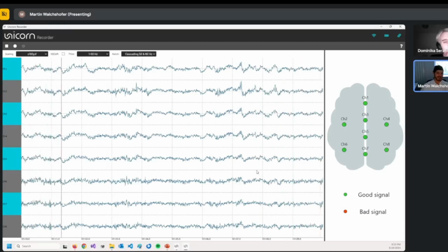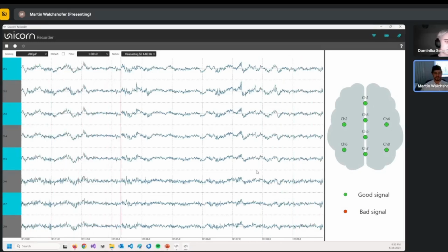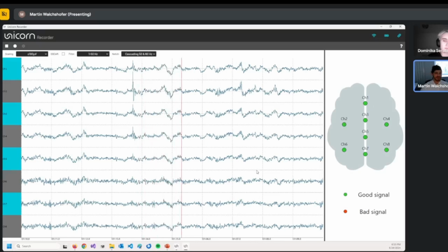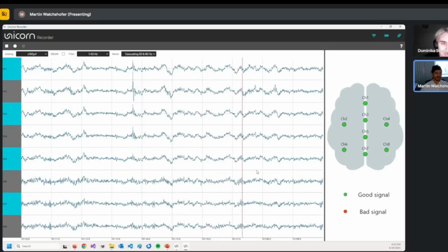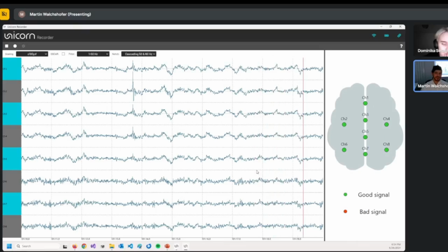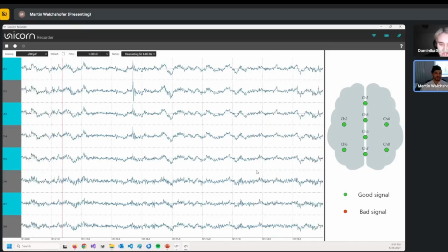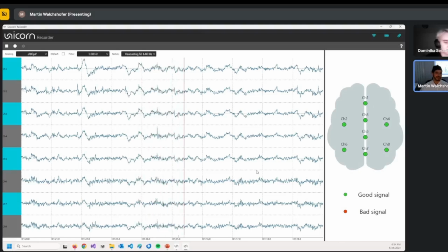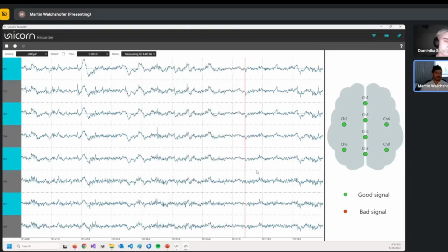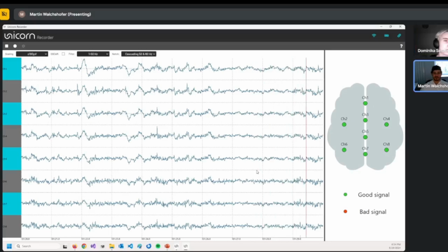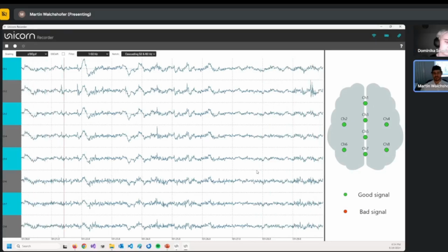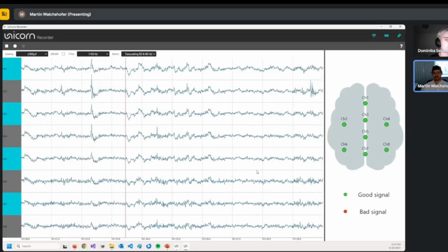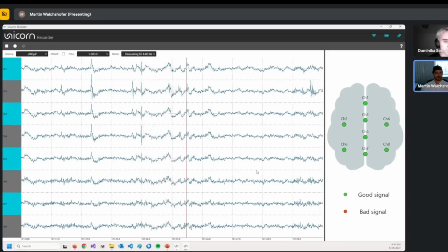So I think if you have good measures to check if the frequency, amplitude range, and so on are valid for EEG, and you can measure the typical artifacts, the typical EEG signals, then that should be good enough, especially for consumer grade BCIs. But I think for most BCIs, the issue is that they're not checking at all if it's an artifact or EEG signal.